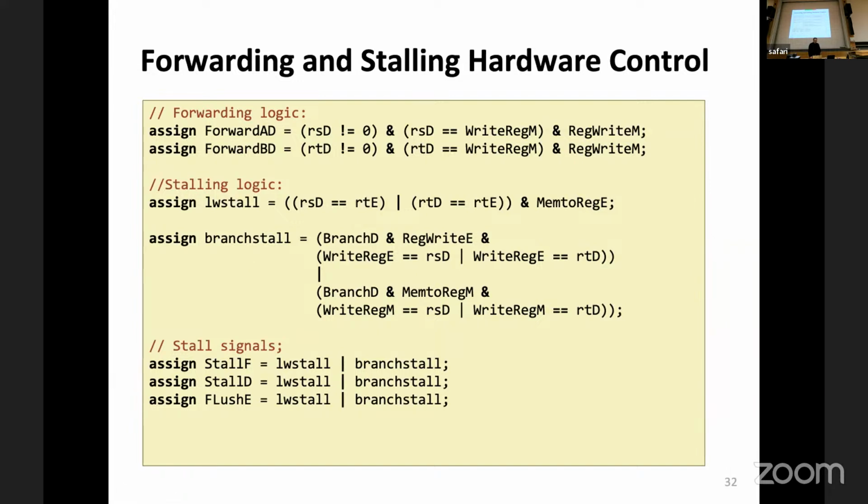So as I said, in the full forwarding pipeline, we will have only stalls for the load word instruction. Basically, we cover all other stalls with our forwarding paths. So you will have this load word stall or branch stall. For branch also, we have one cycle stall. But as I said, this code is quite dependent on our example. In reality, you need to design and see.